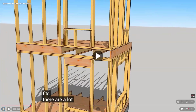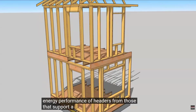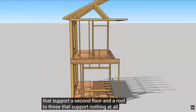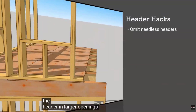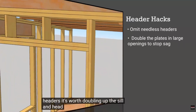Okay, let's go. There are a lot of options for improving energy performance of headers, from those that support a second floor and a roof to those that support nothing at all. If the header supports nothing at all, omit the header. In larger openings with omitted headers, it's worth doubling up the sill and head plates.